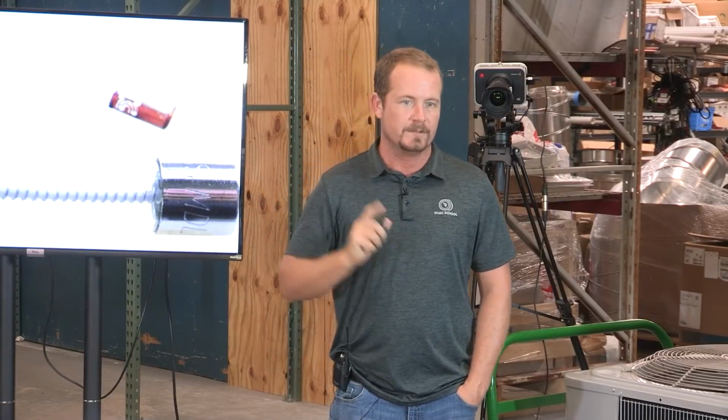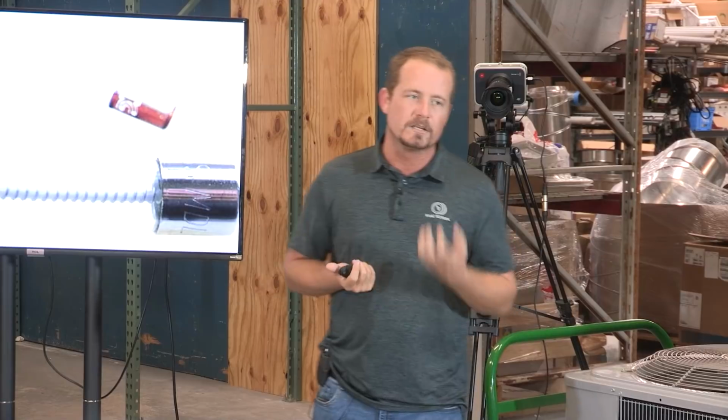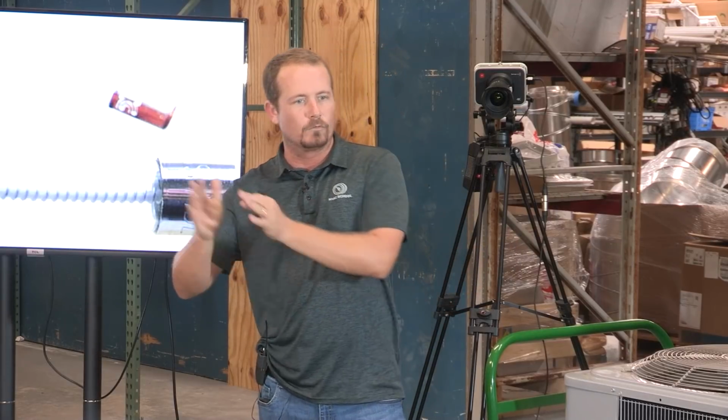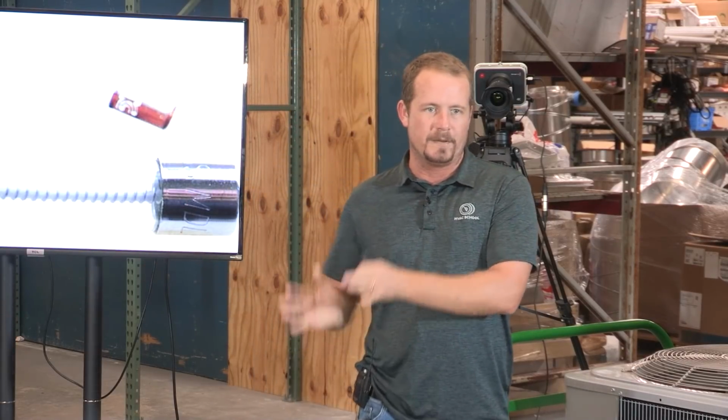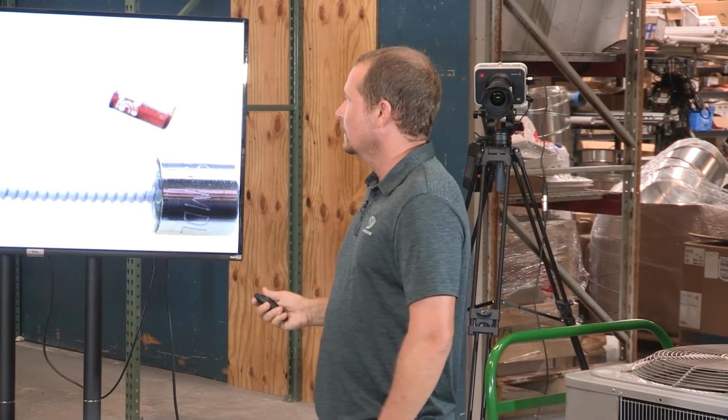Inductive reactance. So it's a type of resistance that builds as that motor gets up to speed, right? And a related concept is back EMF or counter EMF, counter electromotive force. That counter EMF is what creates its own resistance, because a motor also acts as a generator once it starts getting up to speed, because it has these opposing magnetic fields. But the point is when it starts up, it has high current. And if you were designing everything so that it tripped properly when it was at running amps, then it would always be tripping at starting amps. Always be tripping. Straight up tripping, yo.